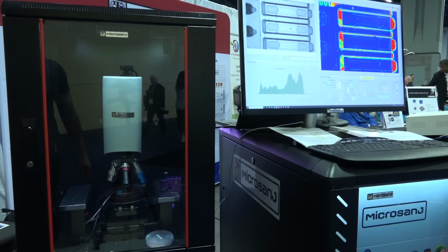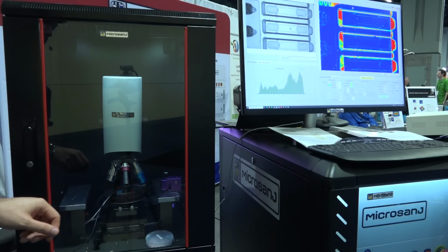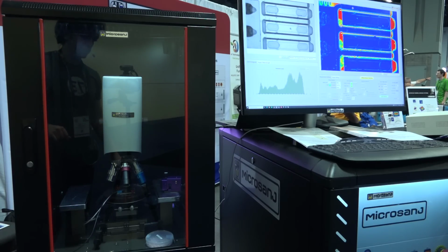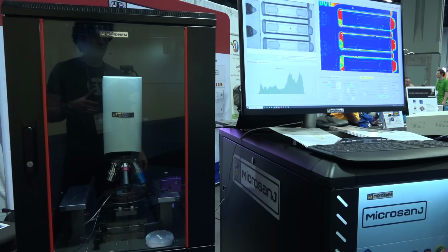So here again at Microsanj, I've actually recorded a few of these videos in the past, but here they're measuring a gallium nitride amplifier device directly on their system. Now if you think about the primary limitation of making general thermal measurements using infrared, it's that the speed of those measurements is slow, and the resolution is low because you need a silicon lens to do that. But in this case, you're measuring it in the wavelength that allows you to use typical optics to get the resolution you want. So you're simultaneously looking at your device in the visible spectrum, but you're also using the Microsanj pulse laser approach to extract the thermal information as well.